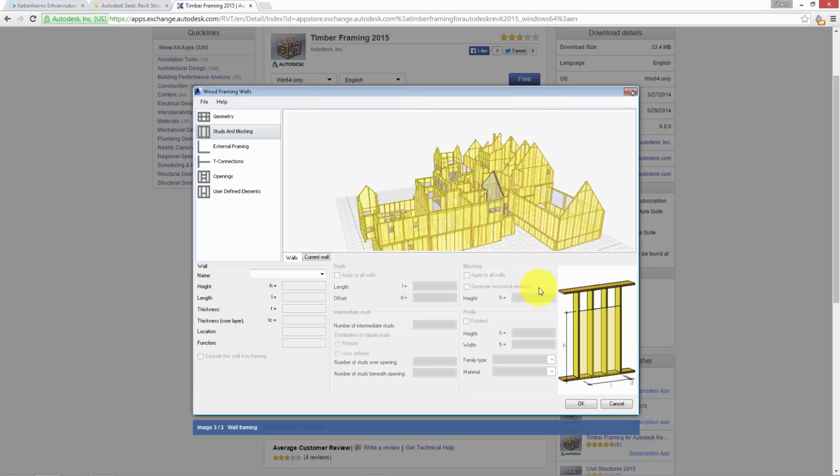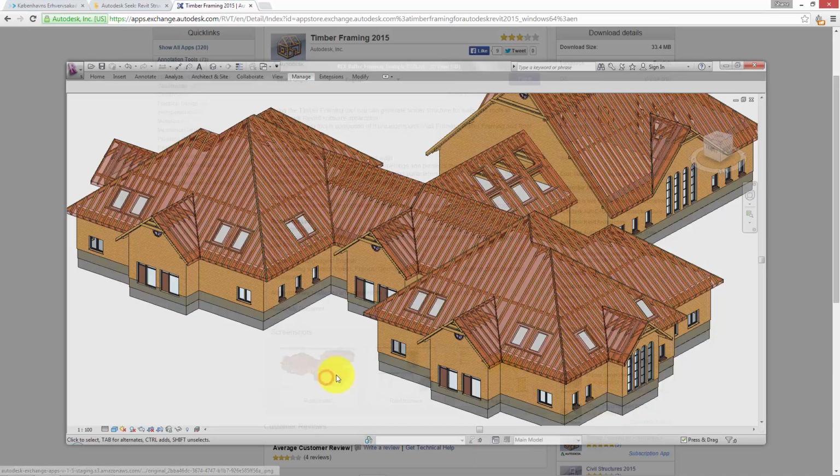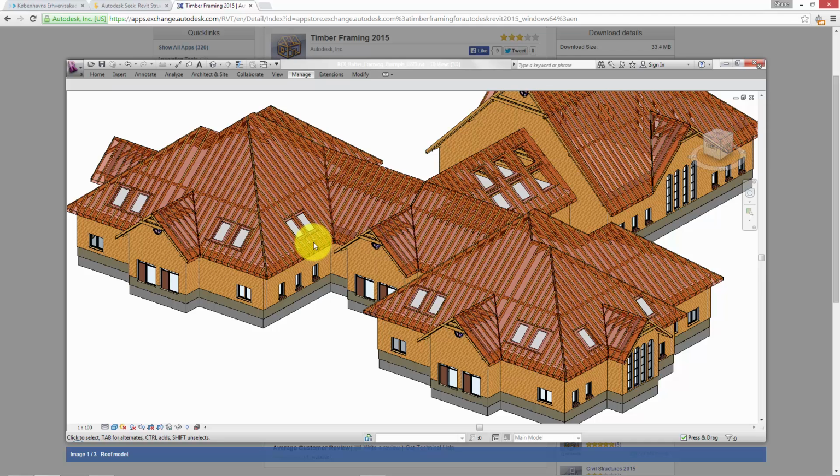And you can set up a start point framing model that allows you to stud out the walls, but it also allows you to set up the roof. It also does a roof structure as well. It's only timber, no. You can change it to any type of beam you want. It's set up for timber mostly, but it doesn't mean you can't play with it.